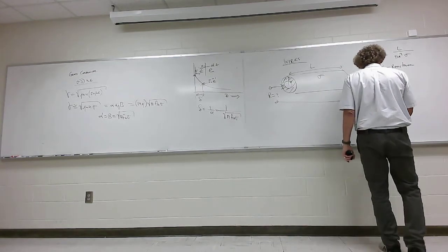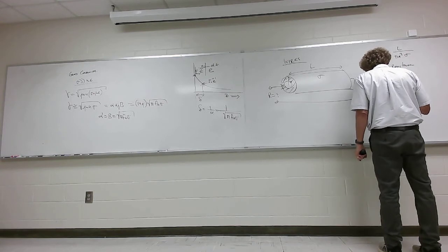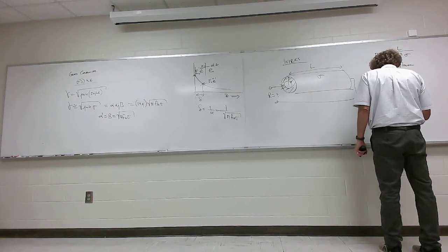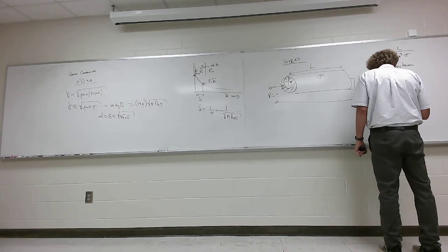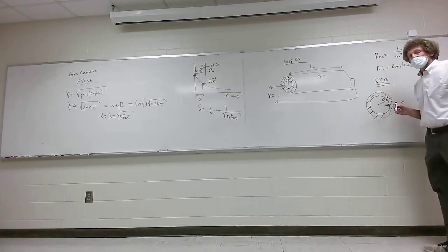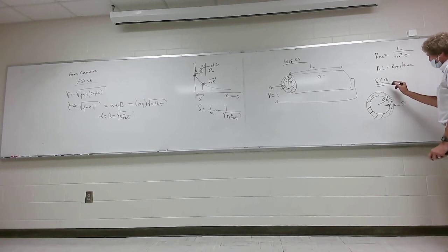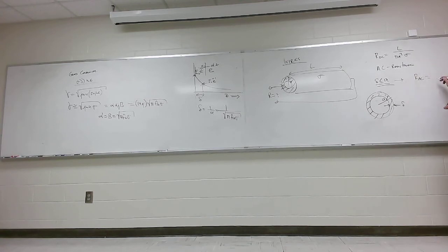So if we looked at the cross section of the wire like this, if this is radius A, and this was a skin depth, I'll get out of your way, here's where all the current is flowing. It's just flowing in one skin depth. I can go formal proof on this, but it kind of defeats the purpose right here. All the current is going to hug the surface of the wire. Y'all follow me? And if that's the case, then the AC resistance will still be proportional to length. Has to be. And it has to be inversely proportional to sigma.